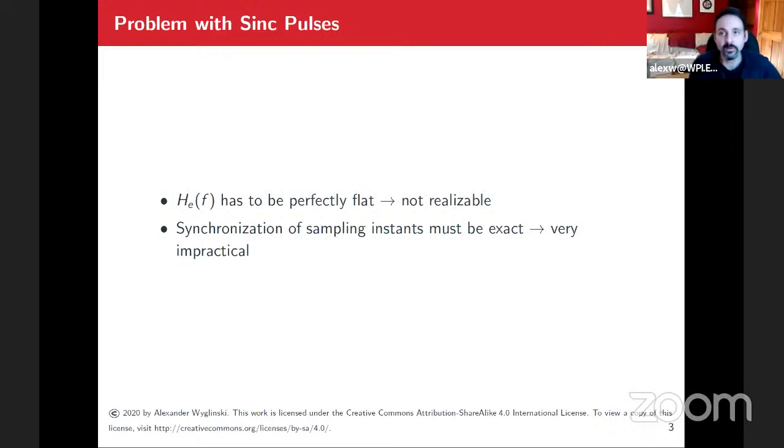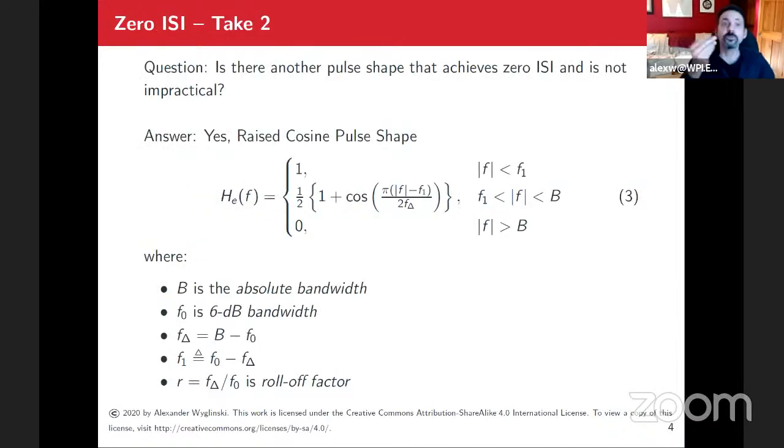And then the problem in the time domain is that you can't have it go from minus infinity to infinity. If you truncate it, you don't have a sinc pulse anymore. And it doesn't satisfy the time domain requirement or the frequency domain requirement. So very impractical. So alternatively, there's this thing called raised cosine pulses. From this point onwards, if you haven't heard about it and you're going to go into the communications world, raised cosine pulses are everywhere. Like, I mean, everywhere. So you're going to see it in every communication system, right?